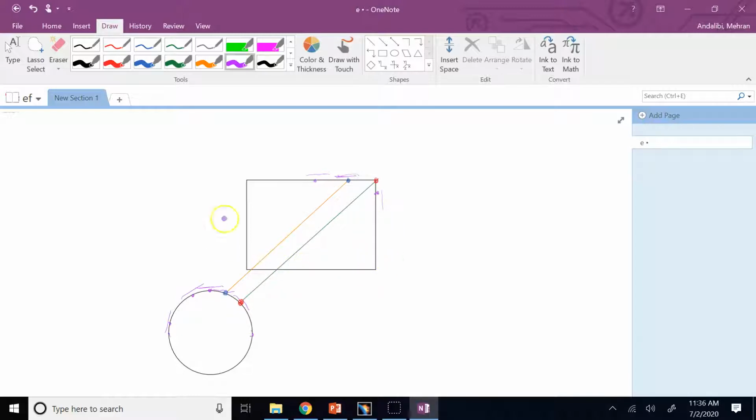If it was another circle, all you need is the extrude command. You don't even need the loft command. But if it was something similar to a circle, like an ellipse, then yes, probably you can connect it to the circle using the tangent method, because an ellipse is smooth as well. But when you have smooth and non-smooth, that method is not going to work. It says use coupling instead.